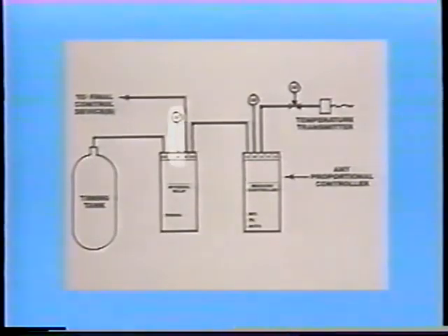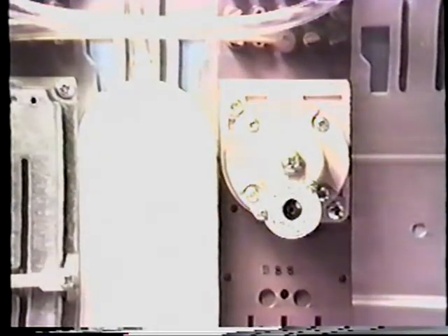The timing tank functions as a reservoir that is used to provide an air reserve to provide the timing effect within the relay. The integral relay incorporates a timing adjustment. This adjustment sets the interval at which the relay looks at the controller's output. This time setting directly affects the response time of the relay to changes in the mechanical and controlled systems to which it is applied.